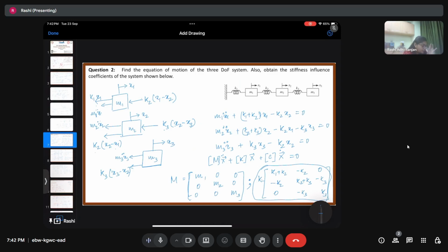It is important to understand that for a 3 degree of freedom system, the eigenvalues and eigenvectors are essentially associated with the modal frequencies and the modal shapes, which means that the eigenvalues are nothing but the natural frequencies of the system, that you can solve also on your own to understand.